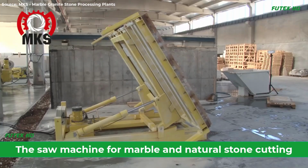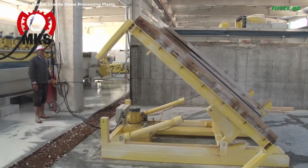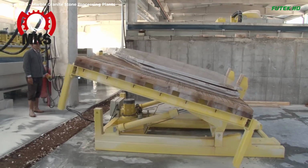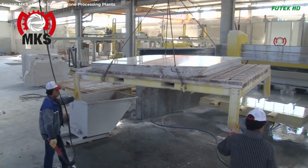The saw machine for marble and natural stone cutting, specifically designed for accurately cutting marble blocks into slabs, operates with a combination of high-tech components and precision engineering. Here's an in-depth look at how it works. The central element of this machine is the blade rack, which is fixed and guided by a hydrostatic linear guide system.